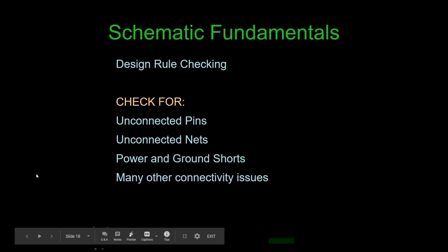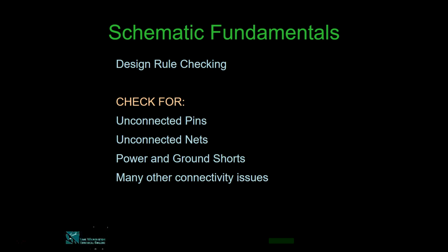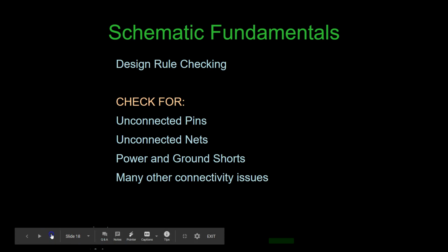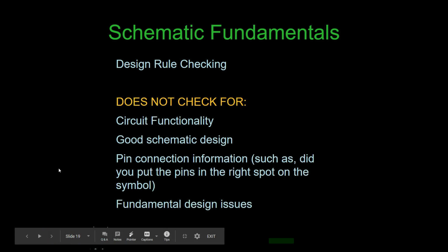Now some design rule check. The KiCad software basically checks for unconnected pins, unconnected nets, power and ground shorts, and many other connectivity issues. It does not check for circuit functionality.